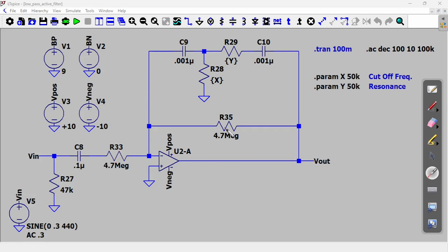And here you can see the feedback loop. The feedback loop has this guy, and what this does is to make sure that the feedback branch as a whole doesn't have too much impedance or too much resistance. Otherwise, you will have no control over the amplification, and it's probably going to go into saturation.